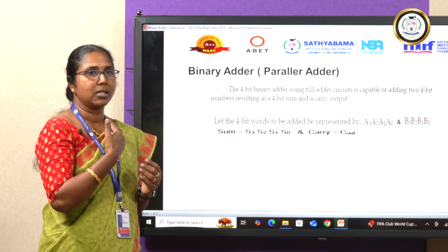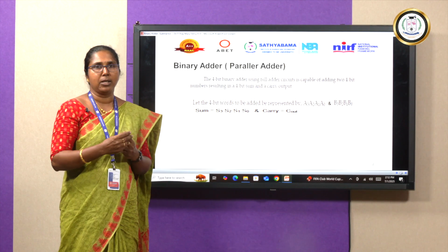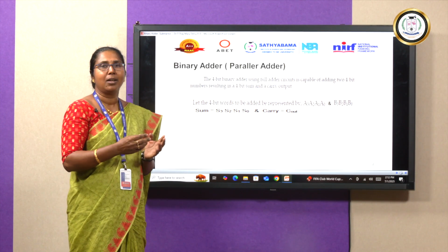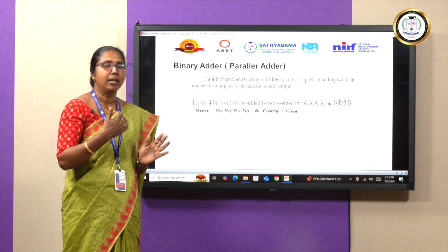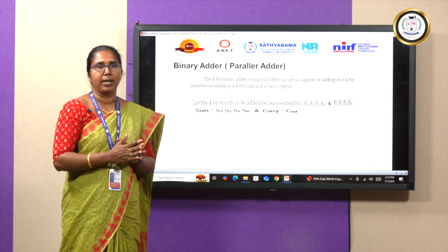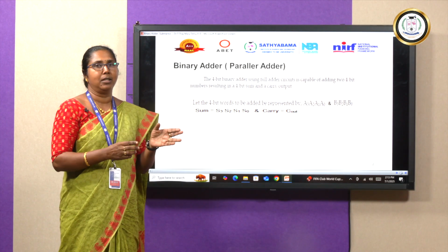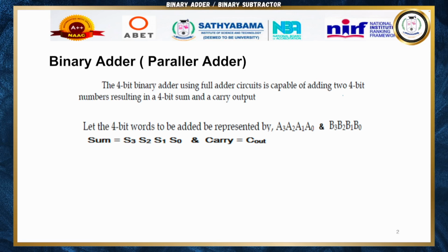Likewise, the addition carries on. If you see, only the first two bits are added using 2-bit addition. But in practice, we cannot split the circuit with the first stage as a half adder and the remaining all as full adders. Rather, we use all the blocks as full adders by taking the carry input of the first stage as equal to 0. So, after adding the 4-bit A and B, we get the 4-bit sum from S3 to S0 and the final carry out C4.